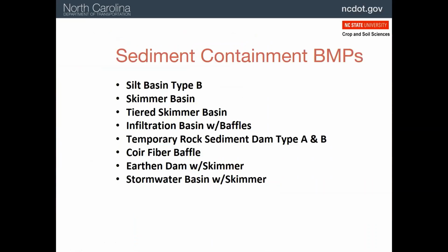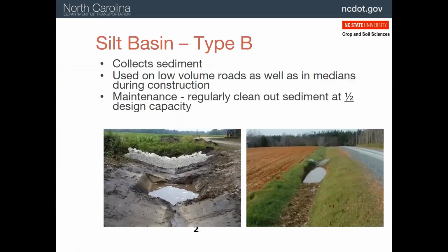So remember that all runoff on a construction site needs to pass through some treatment to remove the sediment. This generally involves pooling the water in order to drop out the larger particles or heavier sediment. But as you can see, there are many ways to achieve that goal. We're going to start with the smallest and easiest and move to the biggest.